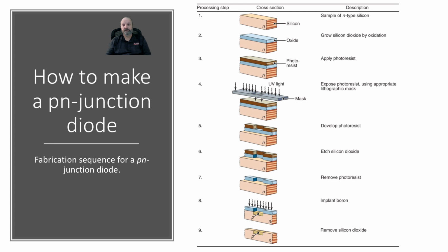So now those oxygen molecules have a lot more energy, a lot more speed, so they can diffuse through the oxide layer you've already created much more easily. So as a result, you can drive some of that oxygen to the silicon oxide interface and cause more silicon oxide to grow. Okay, so raising the temperature helps a lot.